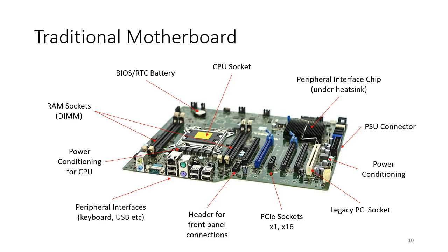Typically for a standard device, you would use standard components. But in an industrial device, you'd be looking at choosing more rugged, longer life versions. For example, electrolytic capacitors, which need to have a longer life without drying out, maybe more rugged power converters, more rugged transistors and so on. They would all be required to extend the life of the device.